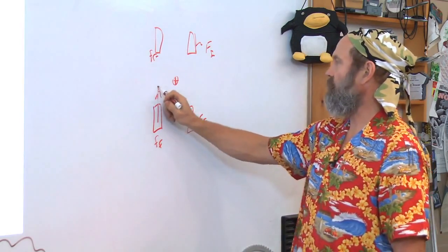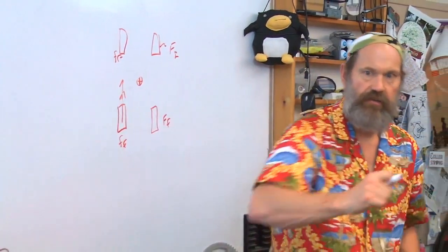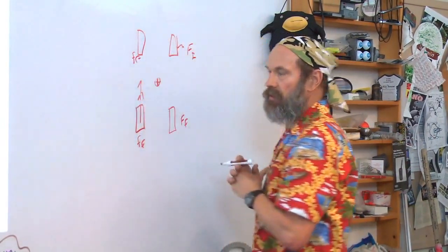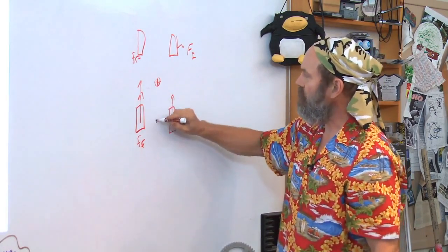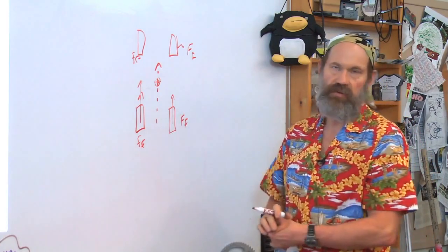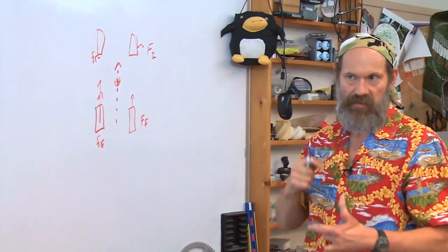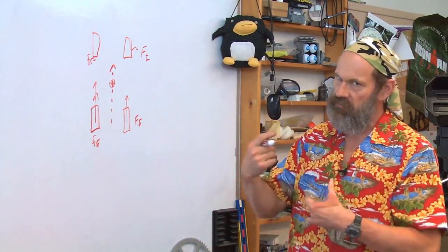If the force to move forward is here, it's going to create a moment and the car is going to go off to one side. So you would always be fighting it with the steering, you'd have slip. If the tractive effort comes from both wheels, the net tractive force goes through the center of friction and you steer straight and you have even wear without having to have any of your steering mechanism move. Okay? Remember, you're always cycling back through fundamentals. What are Newton's laws telling me? Where are the forces? What's the contacts?